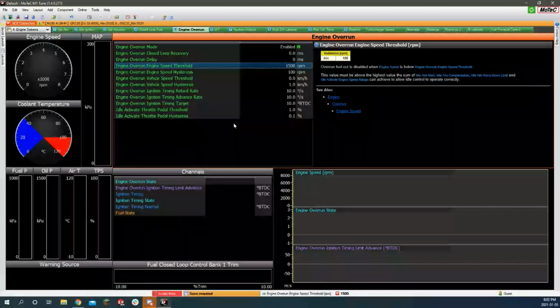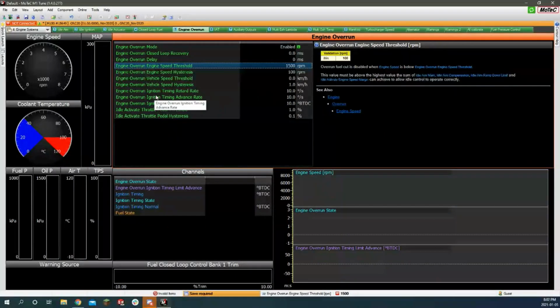And as you decelerate, you'll notice you slow down, but then all of a sudden it starts bucking a bit, and you get a bit of power from the engine. The speed will go up, and it'll go down, it'll go up, and it'll go down. It'll usually sit around 1300 RPM, depending on your temperature, if the engine's warm or not. So all cars do that, and that's to keep it from stalling out.